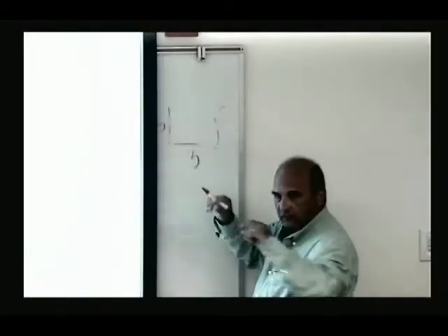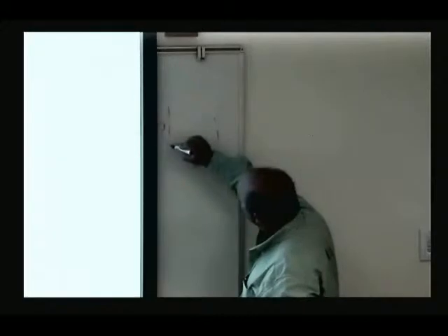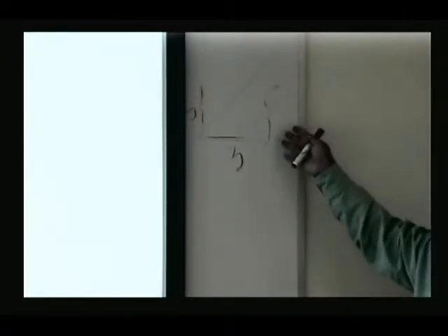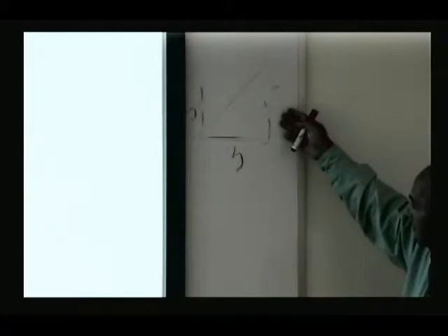That will be your cross area. If you multiply that by the length of your structure, then you know what will be the volume in cubic inches. So you translate that to cubic feet, multiply by 490, and you can get the weight of that structure, at least an approximation.